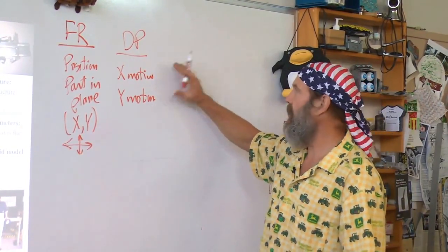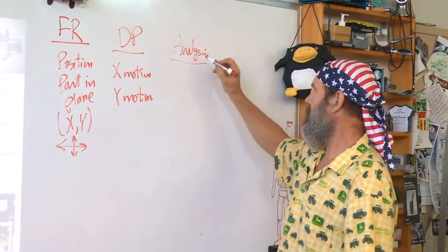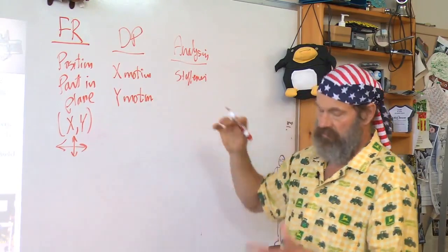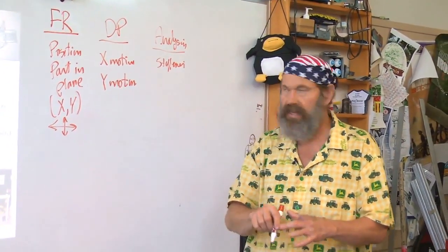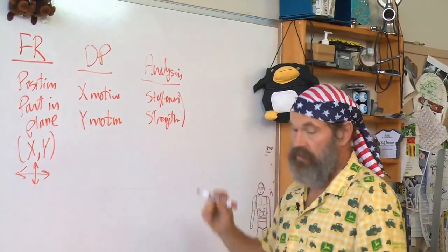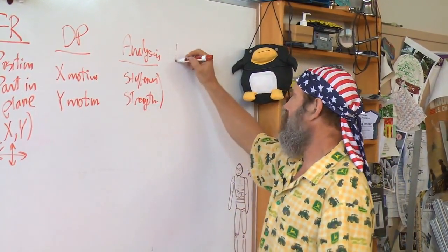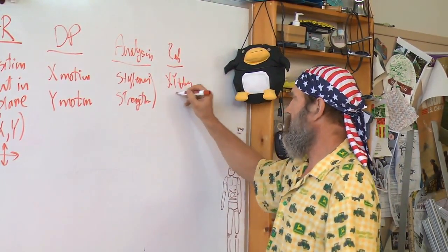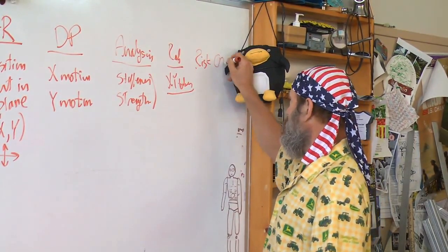I'm going to define the size of these later with my analysis. That's going to be used for my stiffness, which will matter when I'm putting loads from the drill on it. I don't want this thing to sag such that the hole goes through the part at an angle. And the strength, because I don't want someone to come along and push so hard on it that it breaks. And of course, I've got references. There are X, Y tables all over the place. Risks and countermeasures.